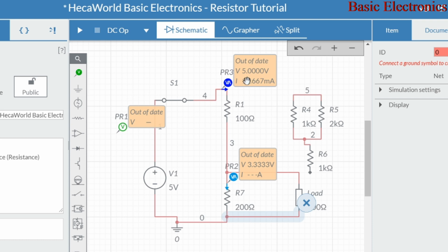You can use this resistor configuration to do that. Some Arduino circuits that you have will require 3.3 volts. Some of them will require 5 volts. If you have such and you have a 5 volt source, now easily you have seen what you can do. You can use two resistors of one value twice the other.